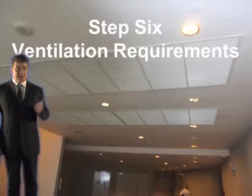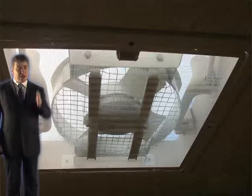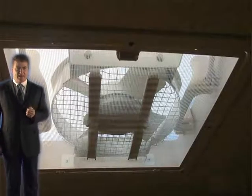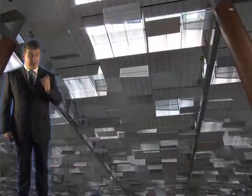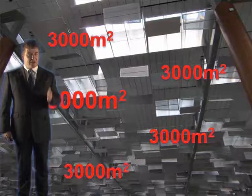Now, step 6 is determining the ventilation requirements. It's been established that we're adopting mechanical ventilation, so let's progress with this in mind. The first thing to determine is the number of reservoirs that you're going to have in your building. The largest size of a reservoir in a mechanical system is 2,600 square metres. However, this can be increased to 3,000 for property protection only. In this case, it's immaterial anyway because there's only one reservoir and it's got a size of 1,450 square metres.